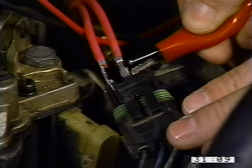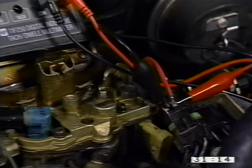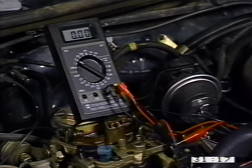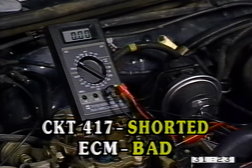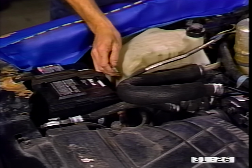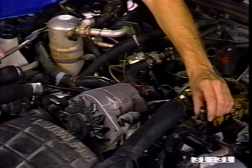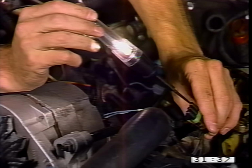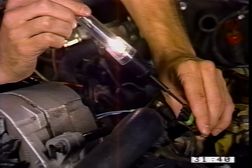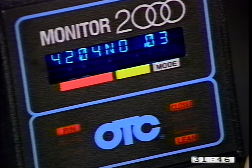If the TPS does display in excess of 2.5 volts, then disconnect the sensor. The multimeter should now show less than 0.2 of a volt. If it doesn't, either circuit 417 is shorted to voltage or the ECM is bad. If there is less than 0.2 of a volt, then probe the sensor's ground circuit with a test light that's connected to battery voltage. If the light stays off, there is either an open sensor ground circuit or a bad ECM. If the light comes on, there is either a faulty connection or the sensor is bad. All codes should now be cleared and closed-loop operation confirmed. The service engine soon light should not be illuminated.